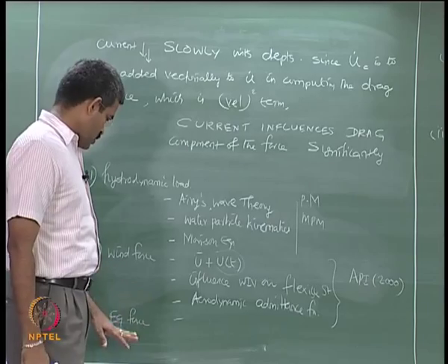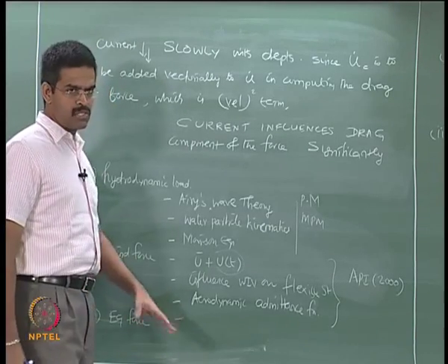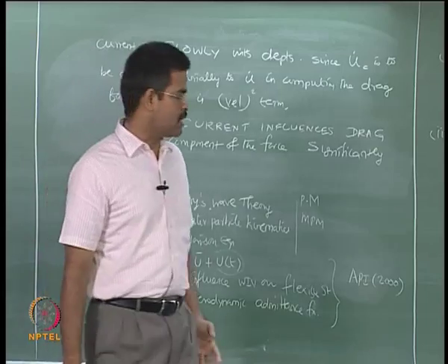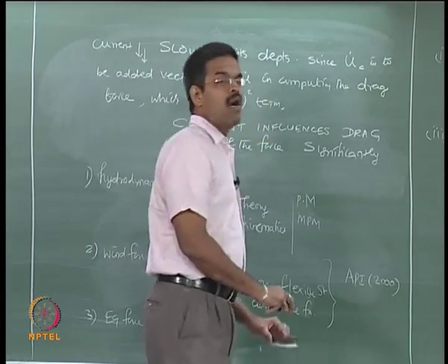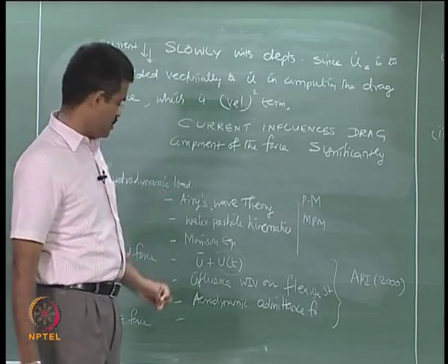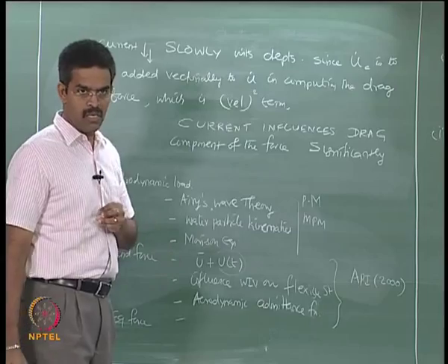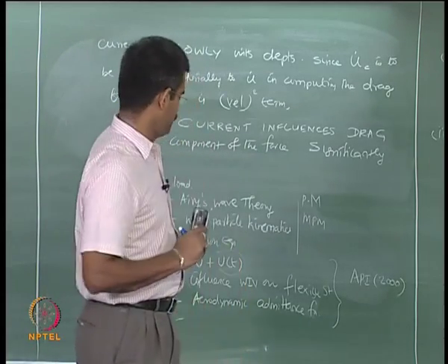When they are bottom supported, it is directly superimposed, but that does not mean earthquake forces cannot influence structures which are in taut mode. We picked up an example in the last lecture. We showed you how a taut mode system like a TLP can also be influenced significantly by an earthquake force, by an indirect mechanism which is suggested by various research in the literature.